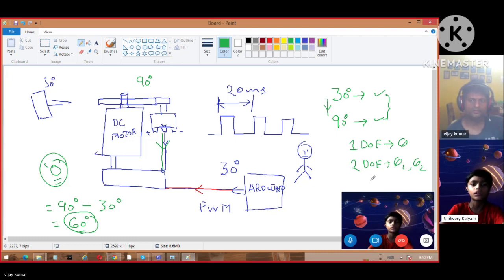Maze solver is over, right, sir? How are we going to use servo motors? We'll use a servo motor in the maze solving robot, where we will mount one ultrasonic sensor on top of the servo motor so that it can sweep some 100 degrees of angle, and it can check the obstacles at front, left, and right, and then take a decision on where to move. Got it? Yeah. Sure, Puneet.